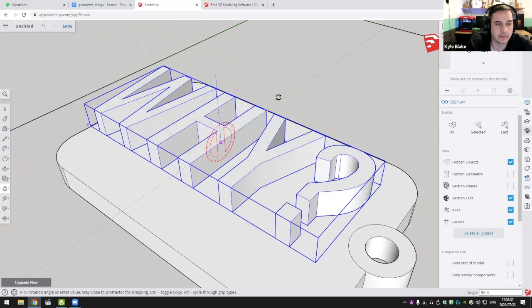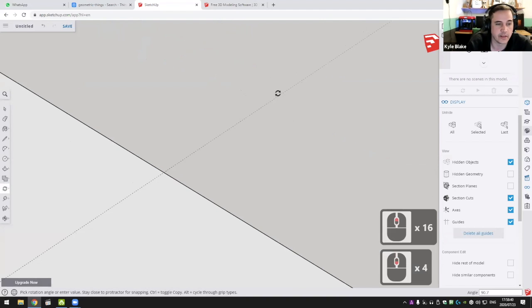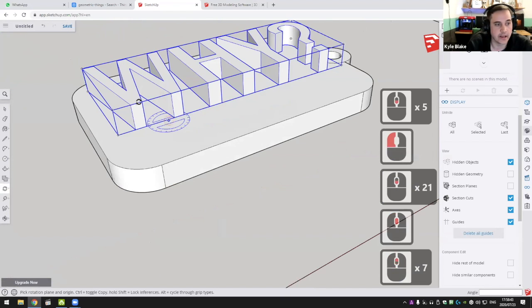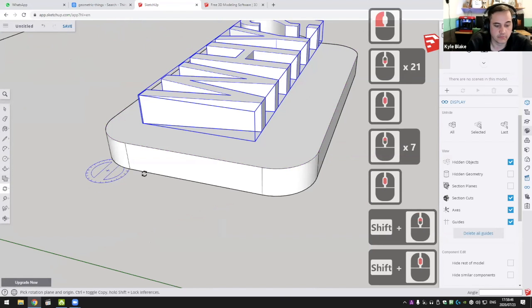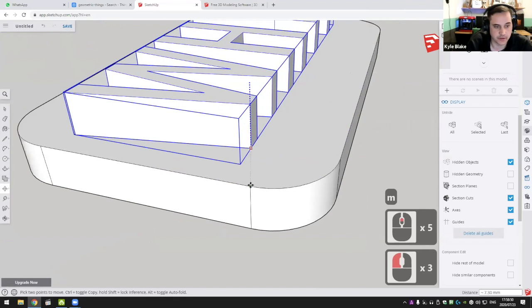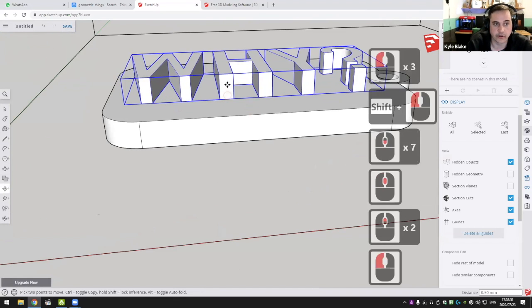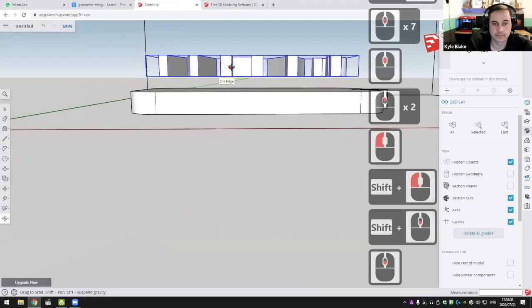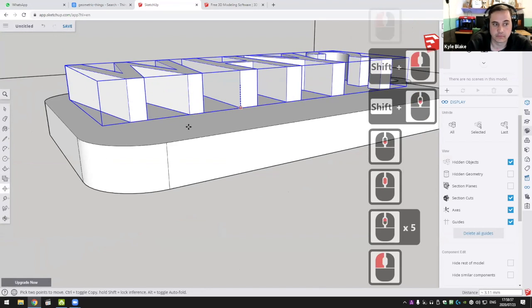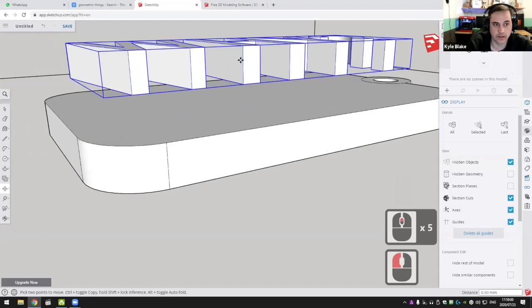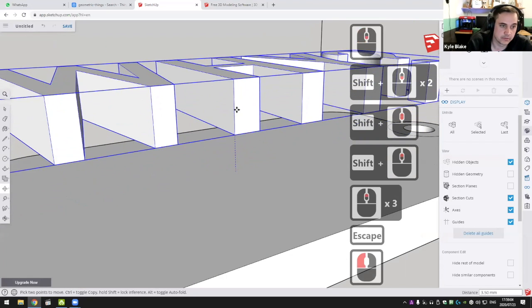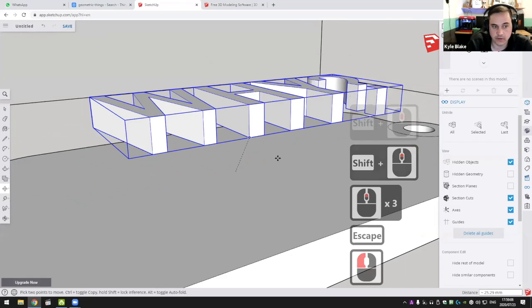It will snap on the green plane. You can see a very light shimmer of green there when it is on a flat plane. Then you can move it to make sure that the bottom of it touches your name tag and it's not hovering like that. So you can just select the corner. If you hold shift down and select the corner, I can move it up, which is on the blue plane. I can move it to the right.